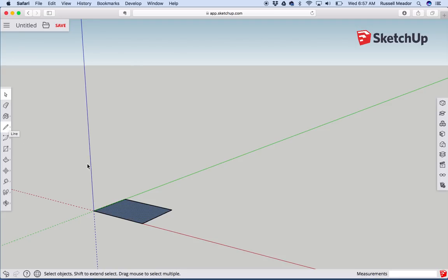So what I'm going to do real quick, I'm going to skip down. We're going to come back up to these tools. But I want to skip down, because this is what really makes SketchUp a 3D rendering program. Let's just click right here on what is called the push-pull. This is really one of the coolest tools. The first time I used this in SketchUp, I just thought it was the coolest. What the push-pull lets you do, when I click that, is bring what I just drew up the blue axis.